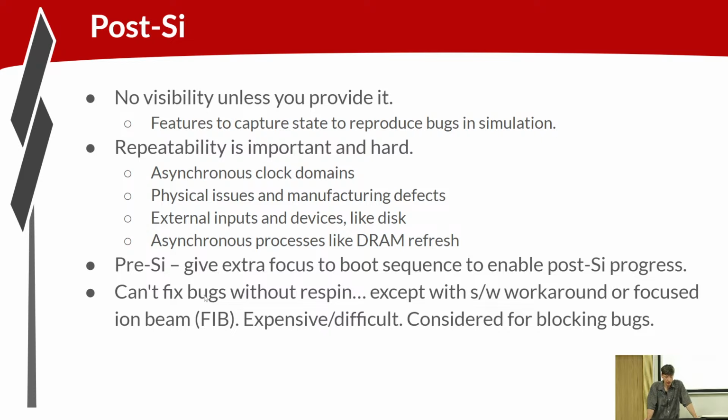Bugs that are found post-silicon, the fix to them means you fix your model and you do another tape out. It's obviously very expensive. So we need to do some things to mitigate the risk that we have to do another respin to fix post-silicon issues.